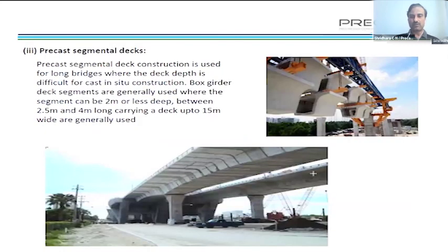And some people will go with segmental decks. Even all our Indian metro tracks are segmental deck designs. These are precast decks, and they will put them in position. Then they will later post-tension all these decks to transfer the loads and all.